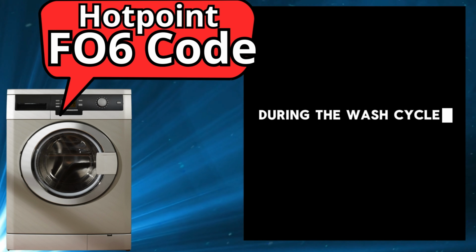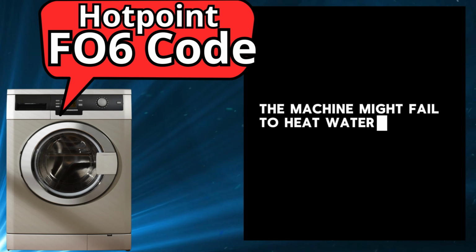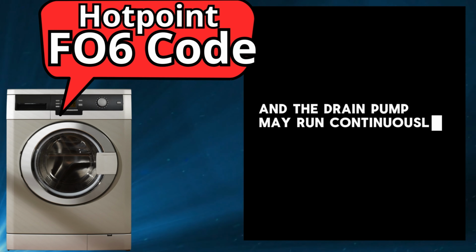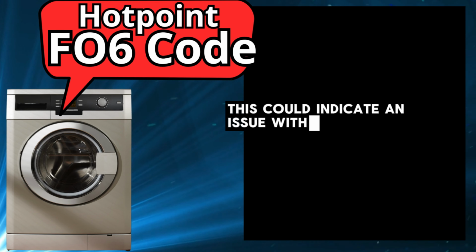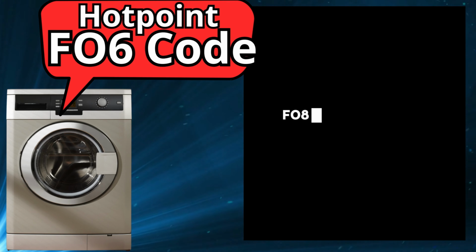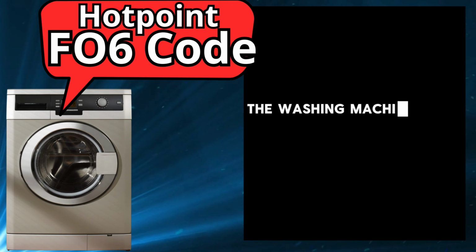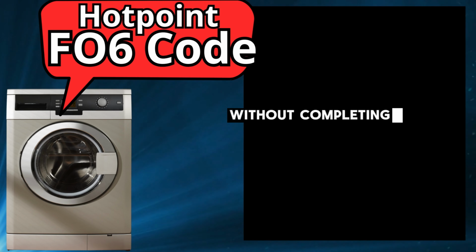During the wash cycle, the program may pause unexpectedly, the machine might fail to heat water, and the drain pump may run continuously. This could indicate an issue with the heating element, the relay, or the control board. F08, heater fault. If this error appears, the washing machine may stop mid-cycle without completing the wash.